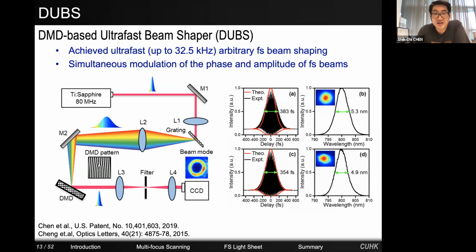And when you encode wavefront information in a hologram, in a sense a binary hologram, displayed on the DMD, you can recreate the stored or designed wavefront by bringing a reference beam to the hologram. As a result, the stored information is going to be recreated. And this pattern here shows a binary mask. As you can see, it only has black and white, two colors.